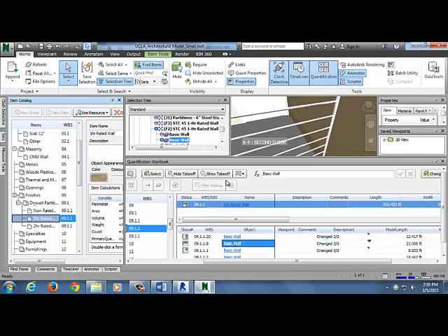But as far as tracking changes, bulletins, they call it, will come out. Before you bid, it's called an addendum that comes out, right? So if you're bidding something, addendum 1 comes out, it changes a bunch of things, new sheets. But after the bid, they call it a bulletin. So same idea, you put RFIs in, they need to update drawings or the model, and they send out a bulletin.